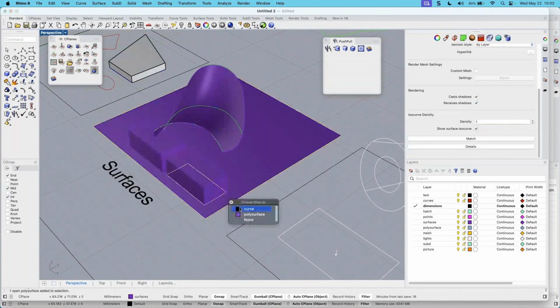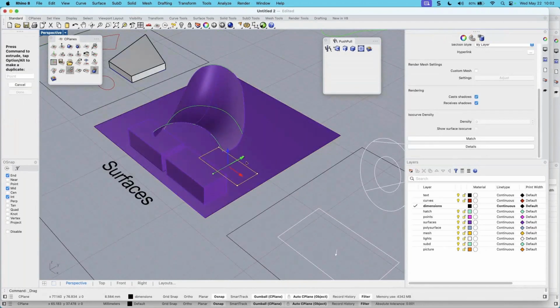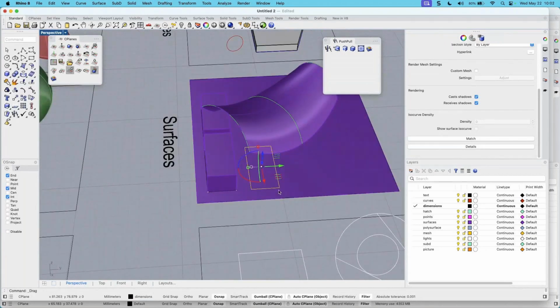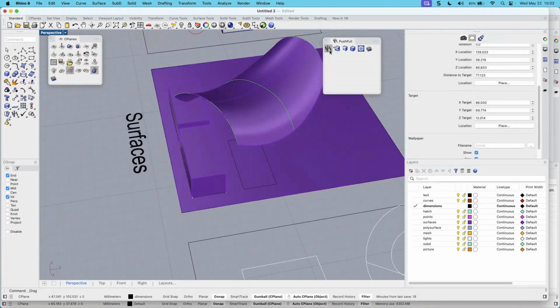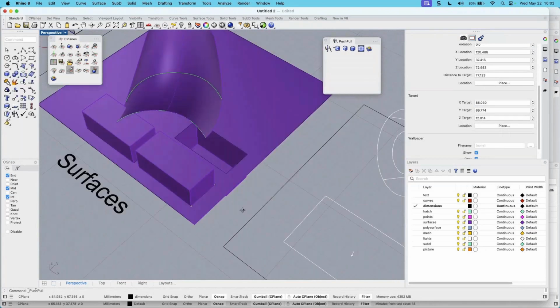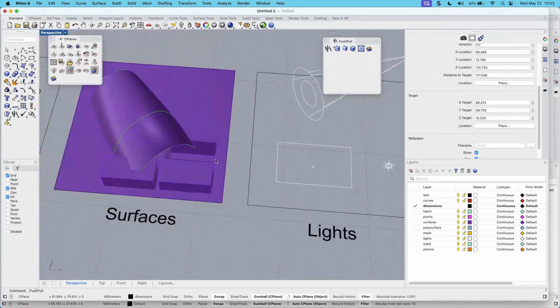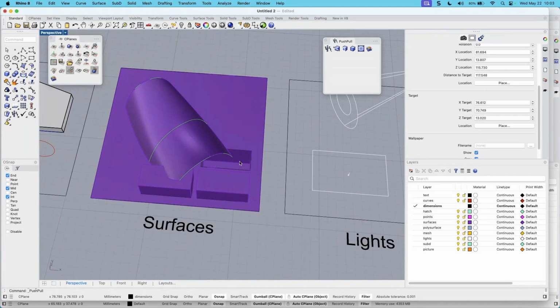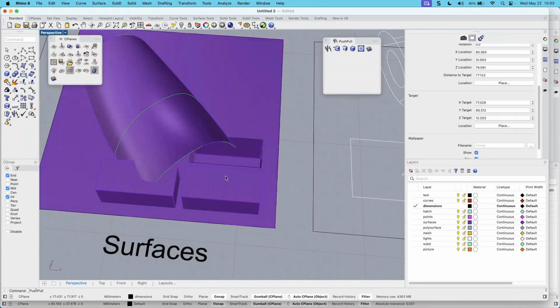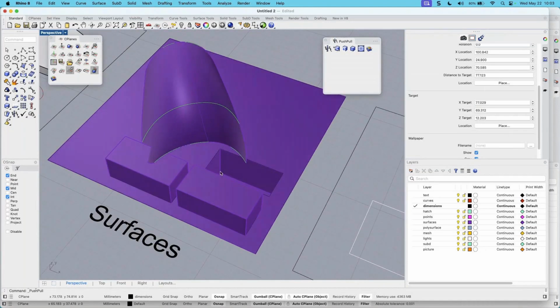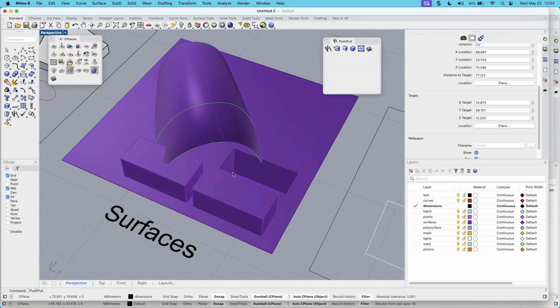So if I take this curve and I copy it over here, tap the Alt key, thank you gumball, and I do push-pull again, I'm going to emboss it. Okay, that we are going to use on the front panel of the shaker cabinet. So push-pull, really great new feature in Rhino 8.